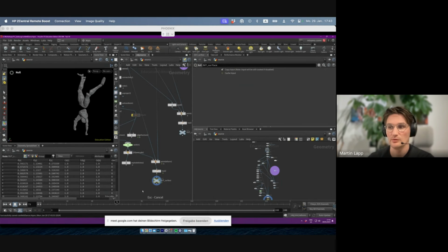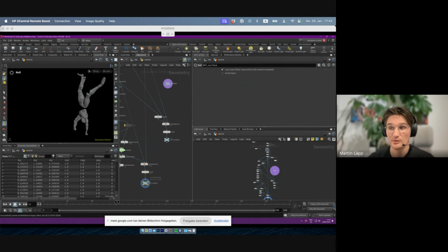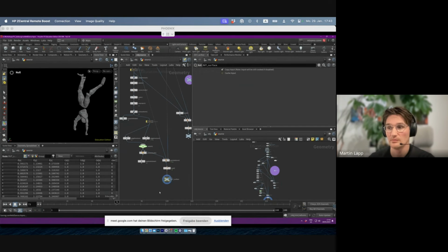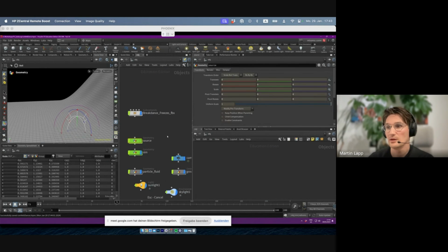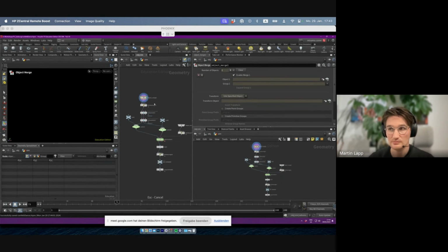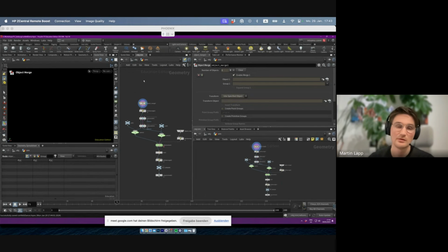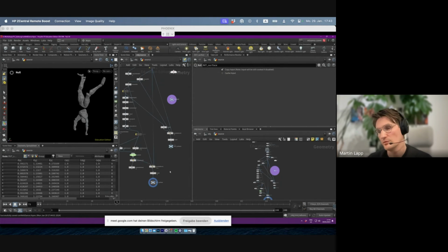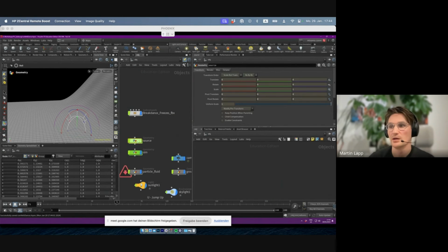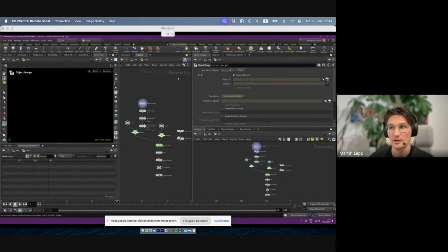And again, I'm using out surface. I didn't even rename the node. Technically, it's wrong because it's not a surface for fluid sim, but it's just an input geometry, but I didn't even care to rename it. And this now goes into, again, the sim. You might notice that last time we looked at the DOP net directly. Here, I'm actually not doing this, just to show that there are also different ways of doing it. So this is SOP land, right? Geometry land here. And my sim is still geometry land because I'm still doing stuff to the source.